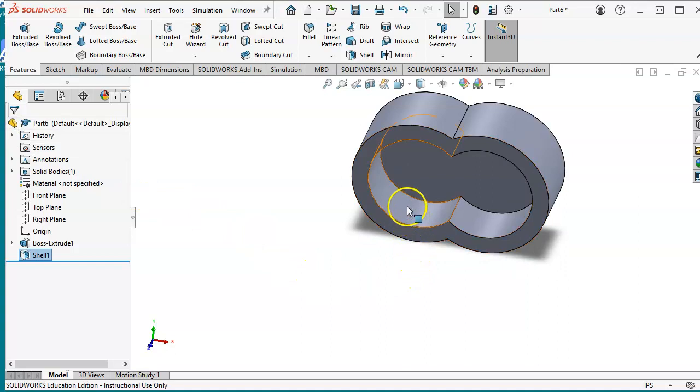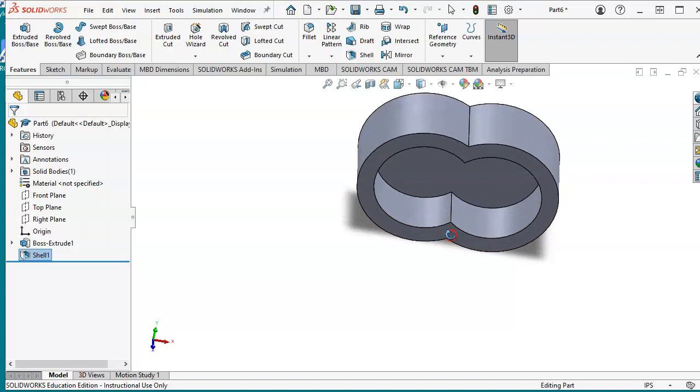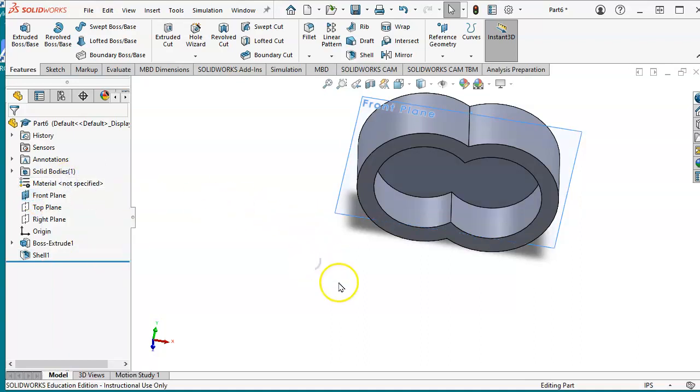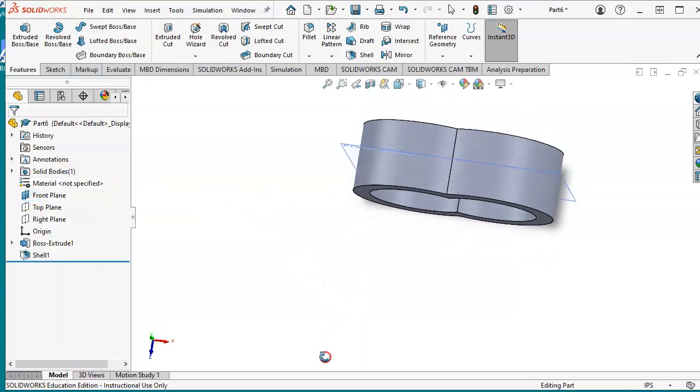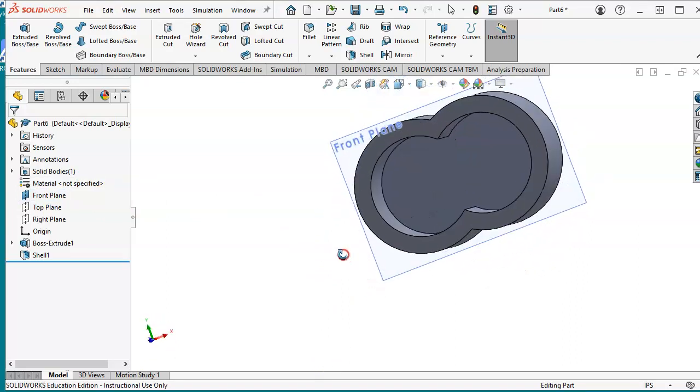Another way would be creating the same geometry by using project geometry and then extrude cut. This is a little bit faster step. So now if you review our planes, let's make this front plane which I created visible by right click and say this is visible. And you notice that my plane is exactly in the middle because I used the mid plane. So by selecting this plane,